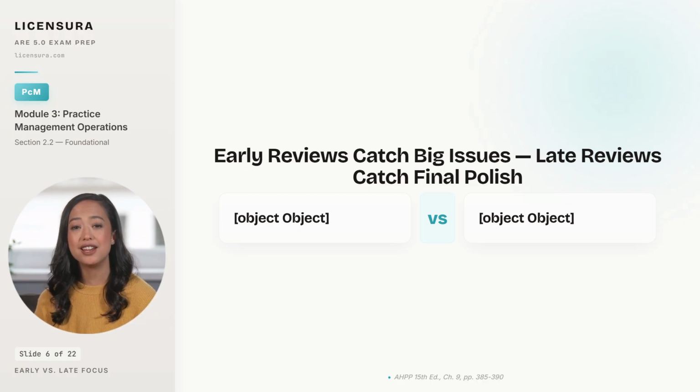A late review at 95% CD or pre-issue is hunting for completeness, a missing sheet reference, an unspecified product, a blank annotation, a call-out that points to a detail that does not exist. There is no time at this stage to redesign anything. The only honest goal is polish on what is already drawn. Detail-focused reviewers lead because the questions are about consistency. If the firm uses senior principals to hunt for typos and junior staff to validate system direction, both reviews fail.